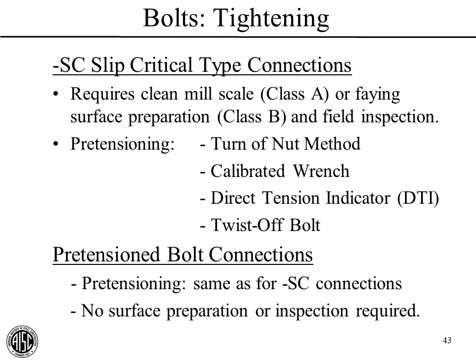So while the idea of indirectly getting the axial load we want using torque is a bit indirect, we do have these 3 methods that do use that method. Note the direct tension indicator is kind of the other way around. It's using the axial deformation to directly measure the deformation of those little nubs, which is in the same direction as the axial force. So it's a more direct measure.